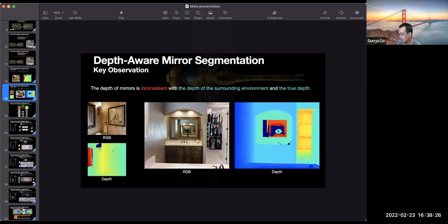Do you think there is some difference in performance? Definitely, because with LiDAR your depth map is much sparser, but now we are using a very dense depth map. But I believe that, with some special treatment, it can be dealt with. Especially since there is a lot of research work that leverages sparse LiDAR for dense depth map reconstruction.